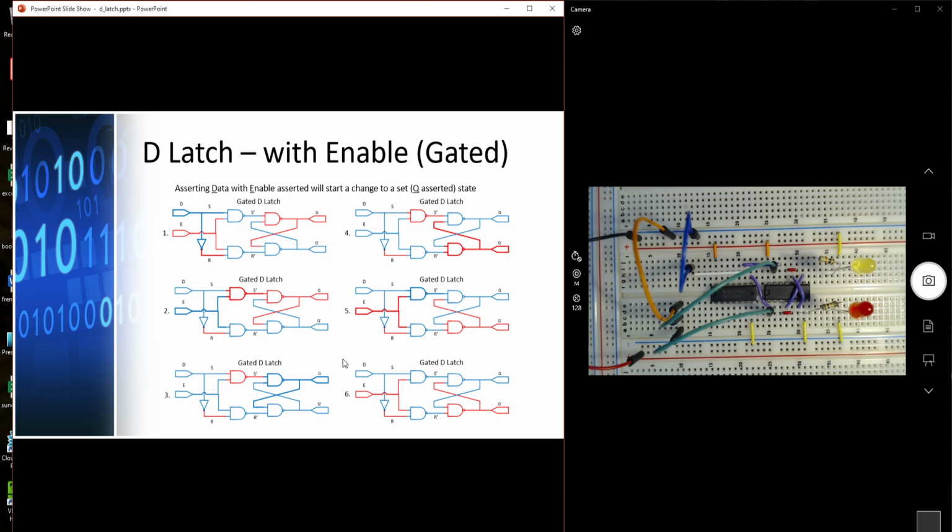With the Q next coming in asserted and the R prime asserted, the lower gate then becomes inactive, and our Q prime is then deasserted, and Q prime next is deasserted. And of course the 0 and the 0 here keep this gate active, so it continues to output a 1. All right, and so then the latch itself is back to a stable state.